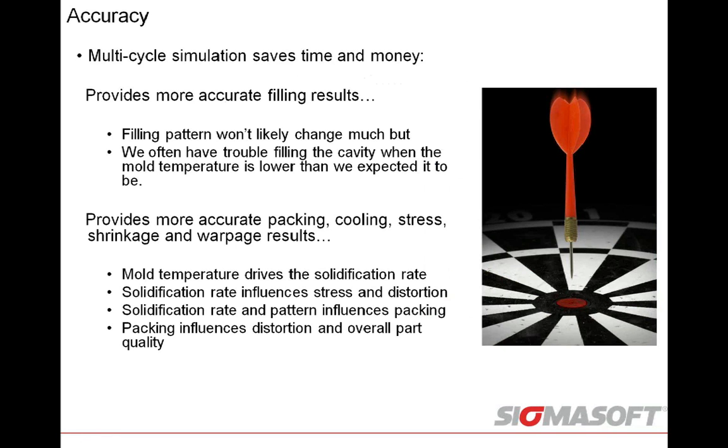We actually give you the ability to bring in the entire mold base, all the mold components, and simulate the entire production cycle: what's happening before the mold closes, after the mold closes, when the part's ejected, even when the part is sitting on that conveyor belt for 30 minutes, 1 hour, 2 hours. What's continuing to happen as that part continues to cool and stresses continue to relax, and the part continues to displace or warp. So if we look at multi-cycle simulation, we can look at it in two areas.